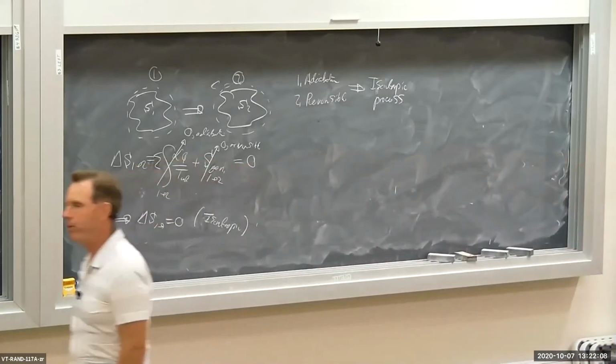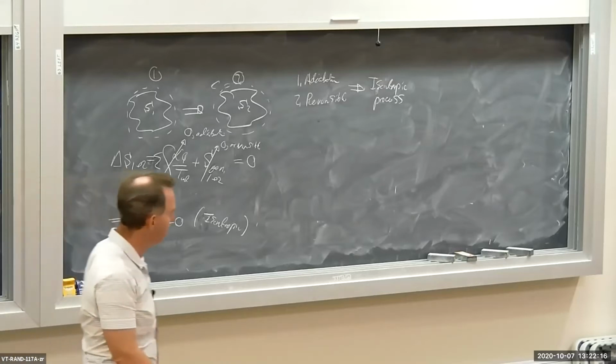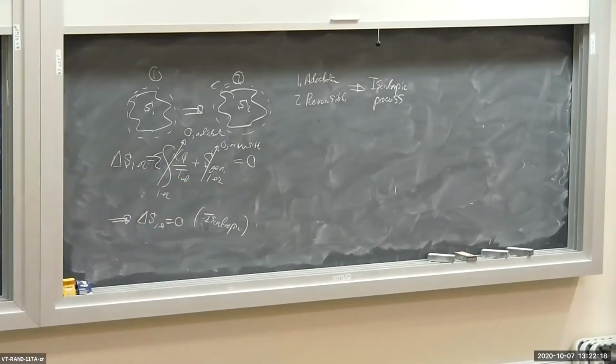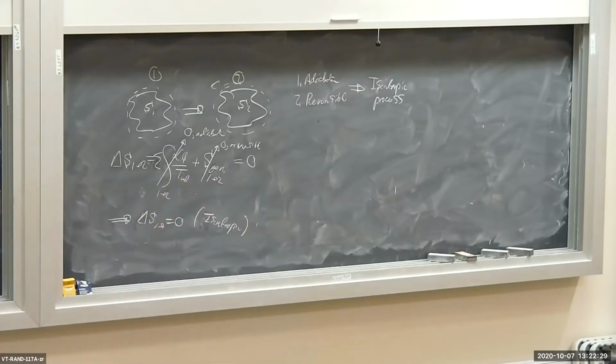So when we have reversible adiabatic processes for a closed system, usually that implies an isentropic process, or delta S is equal to 0. Let's develop some relationships between pressure, temperature, or volume, or specific volume for, let's say, an ideal gas under the constraint of an isentropic process.